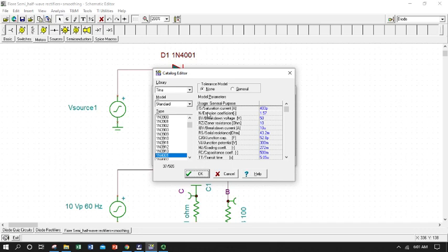Now if we remember the characteristics that might be causing this, thinking back to our diode specs, we know that we're getting current breaking through on the reverse cycle that we shouldn't. The diode is not acting the way we want with reverse bias. So let's look and see if we can't find something that would apply in the reverse bias. And we notice reverse bias breakdown voltage. This is that one you never want to exceed. It's 50 volts. Wow.